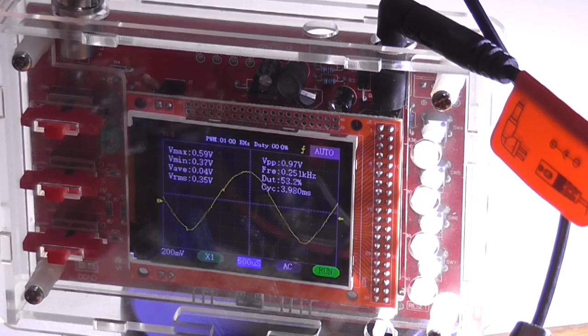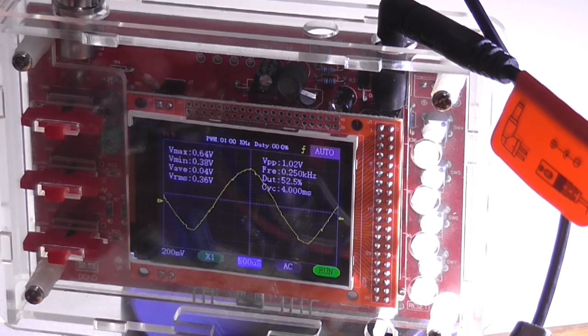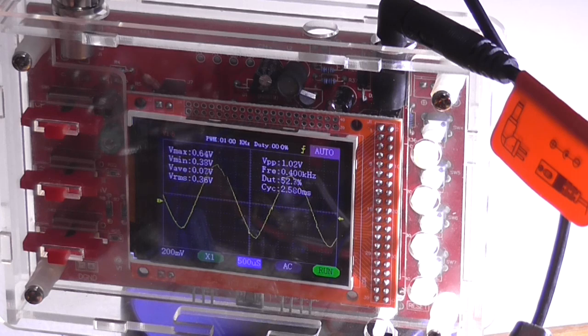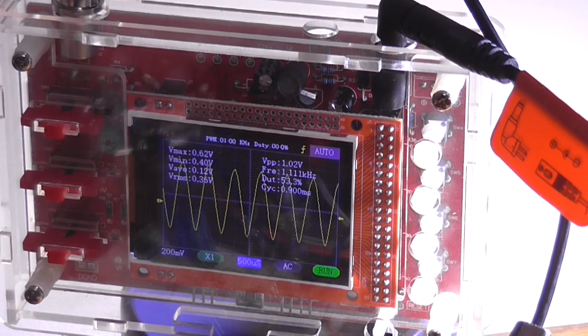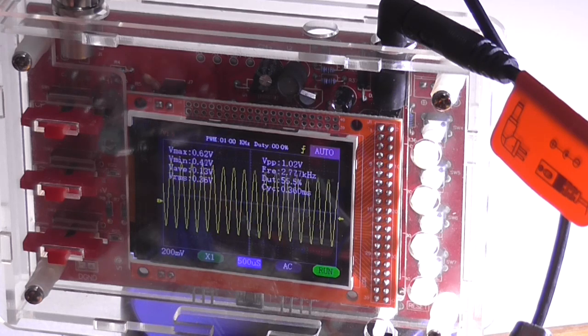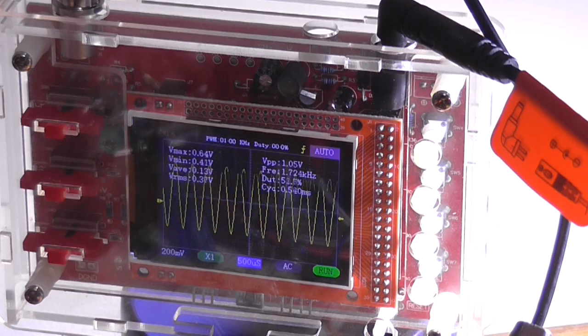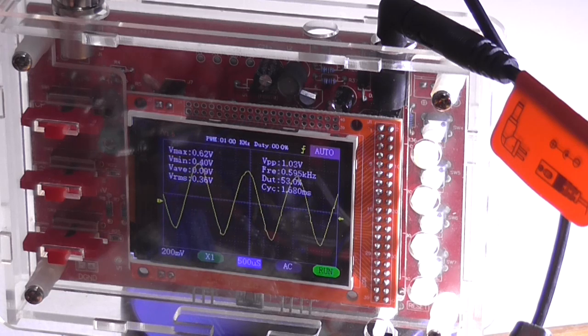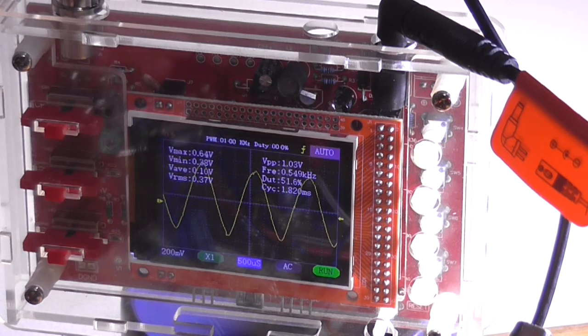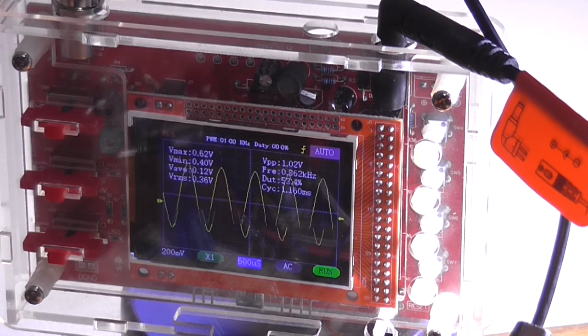And so just for completeness, I'll do the middle frequencies between, well, in this case 250 hertz and the 3 kilohertz we were measuring from before. It's going down, it's going up. Voltage is remaining relatively the same. We're up to 1 kilohertz now. Voltage is jumping up into a couple of millivolts here and there. But no, it's remaining pretty flat along the 170 hertz to 6.5 kilohertz range, and then it starts rolling off at either end, which is to be